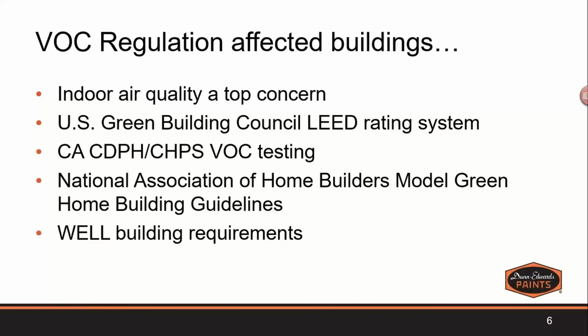So most of us just go by a shorter abbreviation and call it a VOC emission standard or emission report. Another abbreviation that I'm sure you've seen before is CHPS, which is the Collaborative for High Performance Schools. And they allow for low emitting material criteria for schools, which is Section 01350. Either way, these state testings are done through third parties, and they are not done internally from a manufacturer.